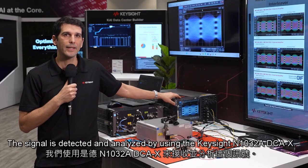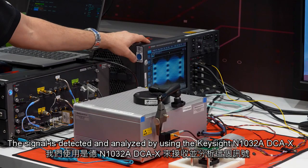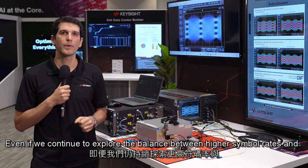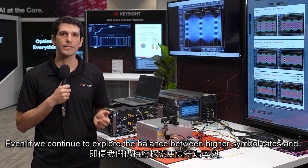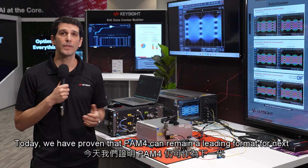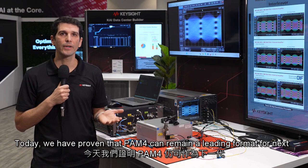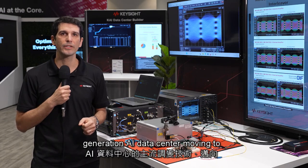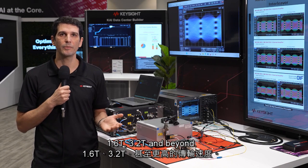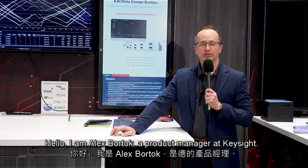The signal is detected and analyzed by using the Keysight N1032A DCA-X. Even if we continue to explore the balance between higher symbol rates and advanced modulation formats like PAM6 and PAM8, today we have proven that PAM4 can remain a leading format for next generation AI data centers moving to 1.6T, 3.2T and beyond.